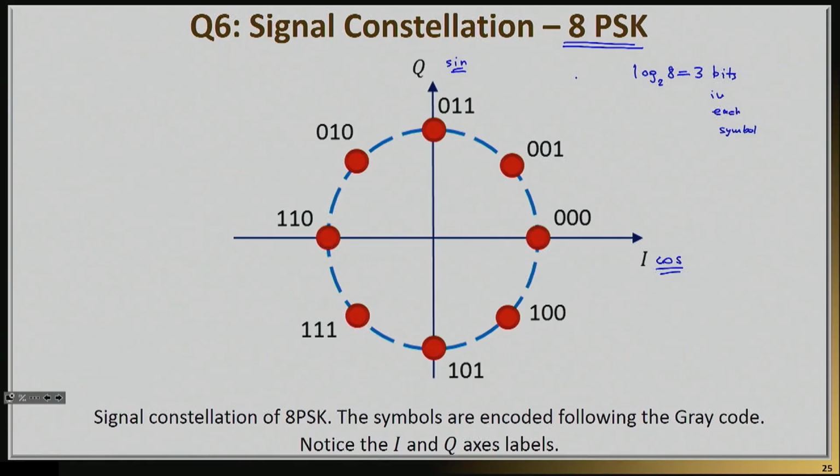So in reality, the receiver knows that it's going to receive one of those 8 symbols that you see here, and all it has to do is decide which of those symbols it actually got. Because of noise, interference, corruption, and all of the other things, it will get a signal somewhere here. And it will say, OK, if this is the signal I received with this much magnitude on cosine and sine, what's the most likely symbol that the transmitter actually sent me? If you were to make a logical decision, you would say probably they sent me this one.